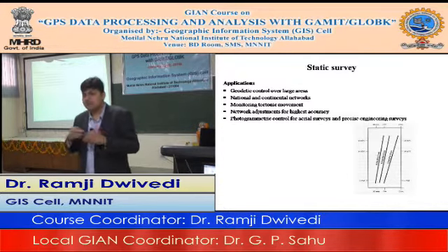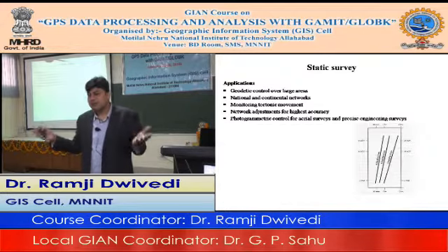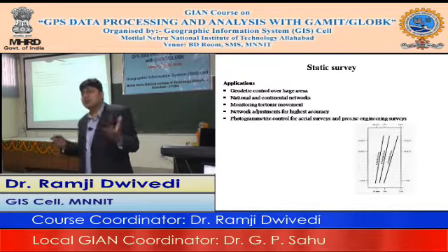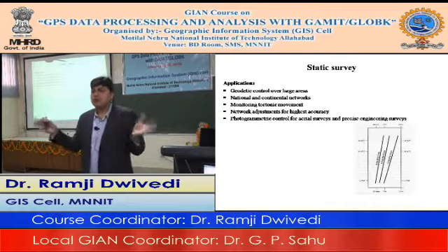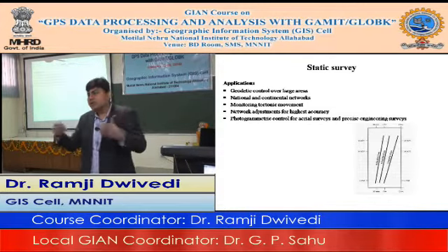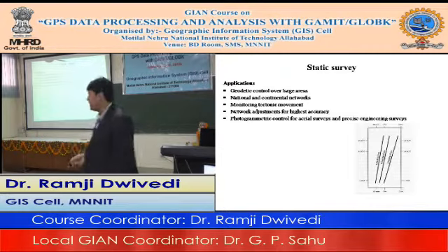So if you are working in a plane area, where you can consider the baseline length like the Kanpur and Allahabad region, in those places you can consider that 1 hour of data with 7 to 8 common satellites, you could achieve the precision which you are thinking about.